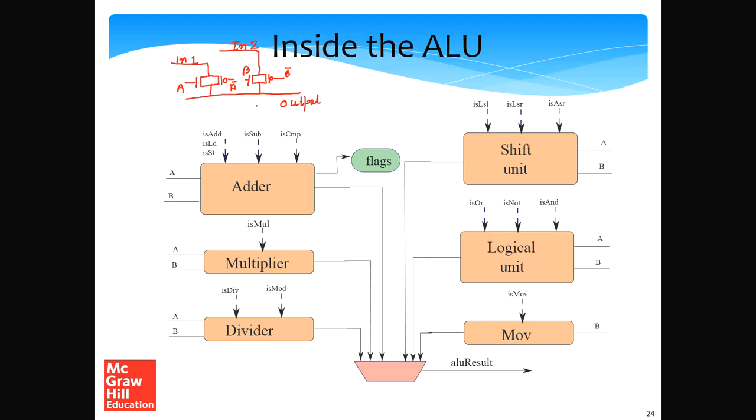Now, if you recall our discussion from chapter 6, let's say that A is 1. If A is 1, the NMOS transistor is on, and A bar is 0, so the PMOS transistor is on. So essentially this input is connected to the output, and the output will take up whatever voltage is there at this input.